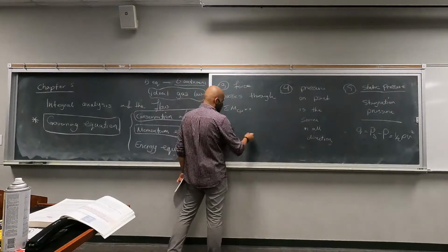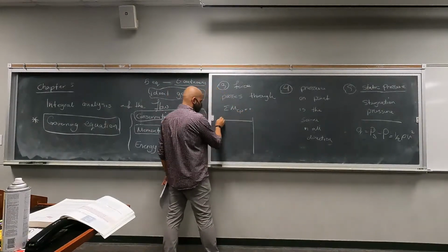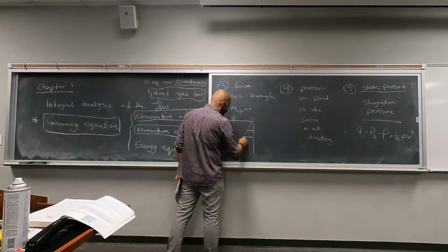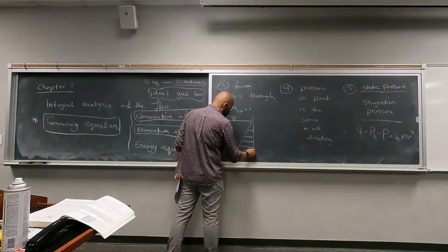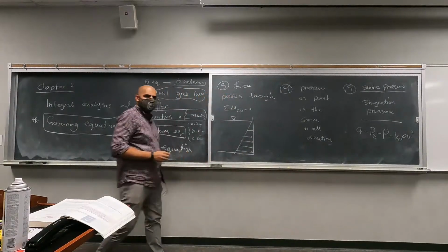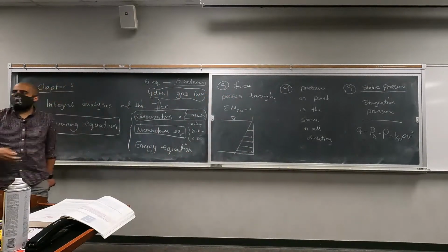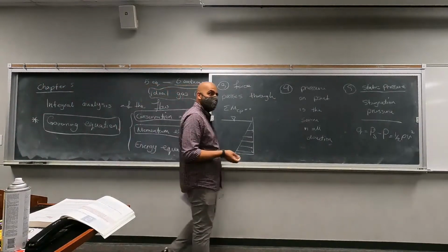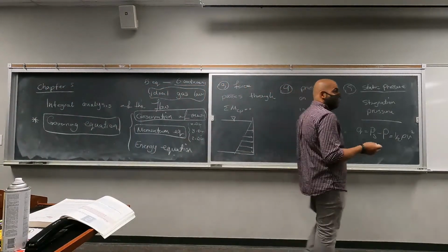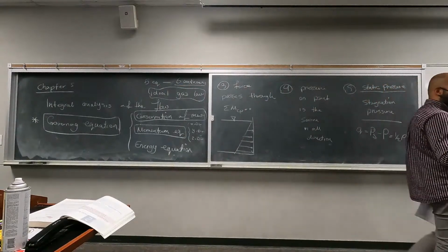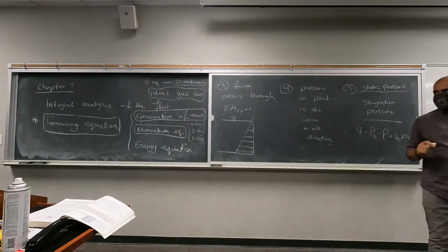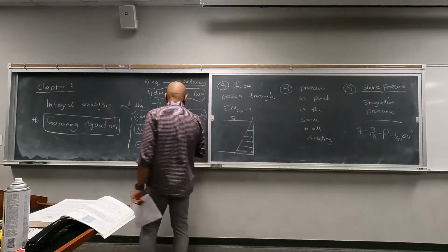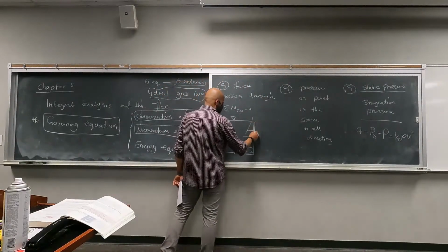To understand this better, let's say we have a free surface, and this is your pressure distribution. The idea was we can replace all of this pressure distribution with a force, right? How did we calculate that force? We calculated rho g multiplied by the depth of the centroid, so gamma times h of c, right?